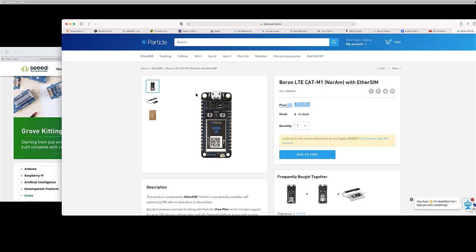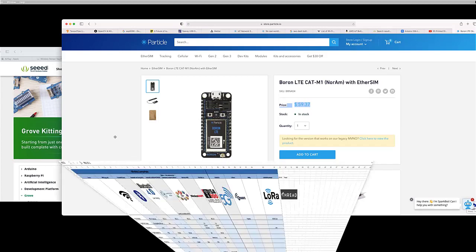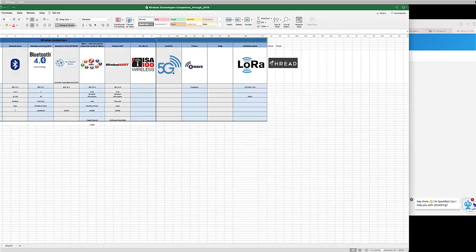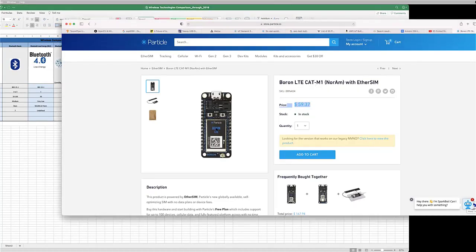But again, if you had one gateway, and attached to that gateway, yeah, correct. So you could potentially have a device like this inside of a gateway, and then much cheaper, lower cost acquisition devices on the line itself. So a cellular modem, that's one of the ways to wirelessly communicate data. But the thing about 3G, 4G, and 5G modems is they're not cheap. They're not as cheap as a 900 megahertz radio.